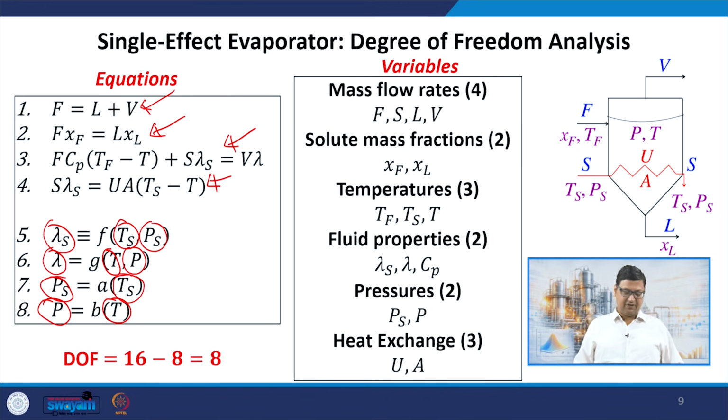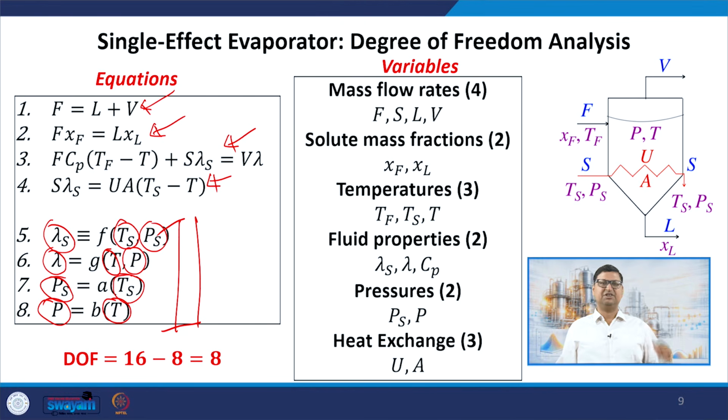So, with that we have in total 8 equations in this case. Although I am listing these now, we will not typically list them in future. We just take it for granted that the latent heats and the pressures may be obtained from the temperature and other conditions from these property relations, right. These are not typically listed, but keep in mind that they must be used here, and they are the equations which make the first 4 equations nonlinear and difficult to solve.